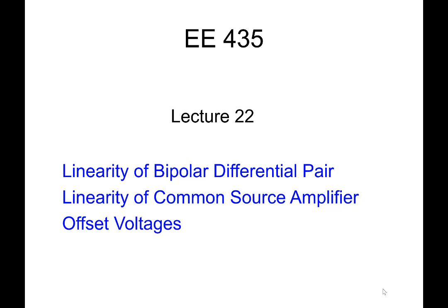We haven't spent much time talking about bipolar transistors in this course. But we looked at a lot of different op-amp architectures. In all those architectures, you can replace all N-channel transistors with NPN devices, all P-channel transistors with PNP devices.